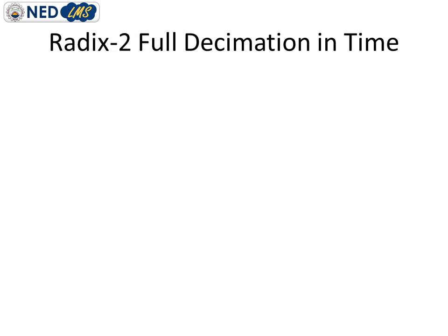For example, if you have 30 values in the sample set, and you know that you can represent 2 raised to power 5 as 32, so you will append 2 zeros in the original signal.